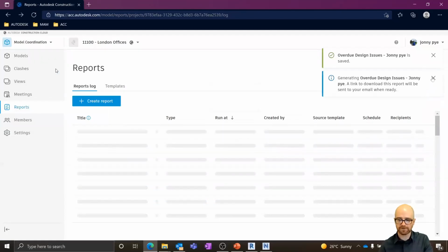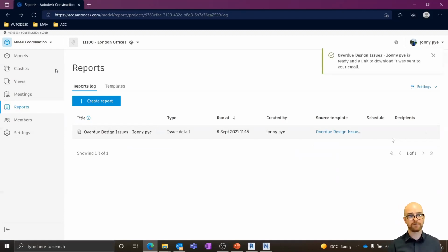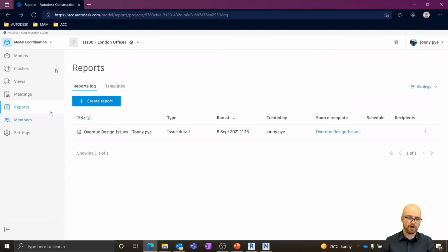So when I'm setting these up as a schedule, once I've run the report, I'll be able to set this up so that you can actually get the reports every week at a specific time. You can have it emailed to you every Monday, and you get a good overview on the project. So there are some really nice, useful reporting features within both Autodesk Docs as well. This capability is in Autodesk Docs, and issues that you might be creating from model coordination perspectives as well. So all the metadata that you put into those issues is going to be very useful throughout the project.